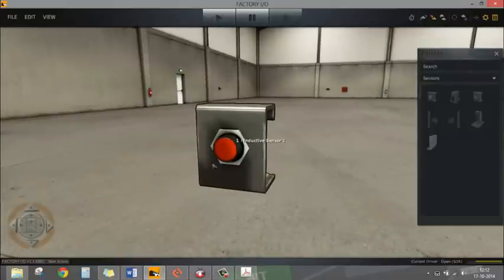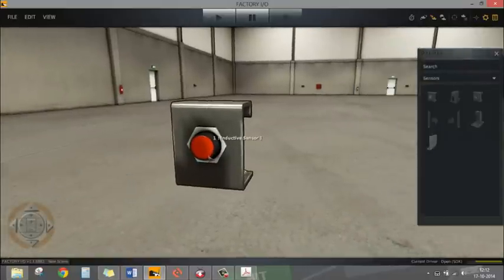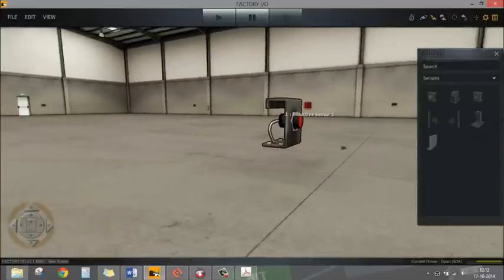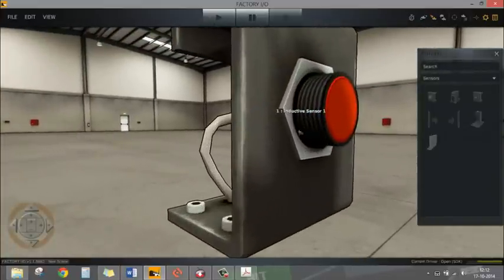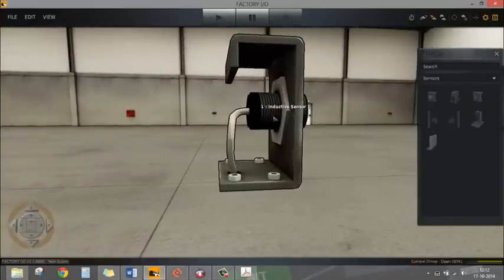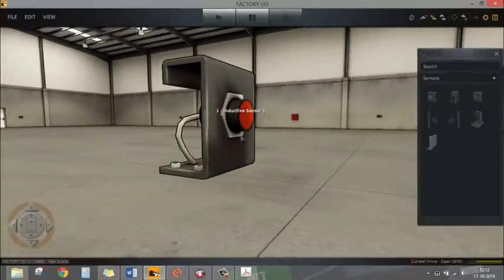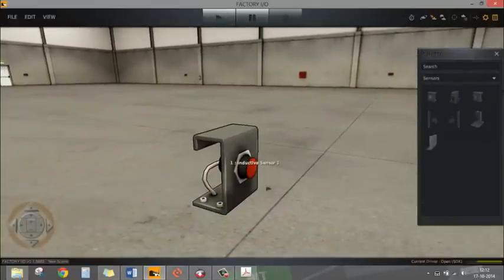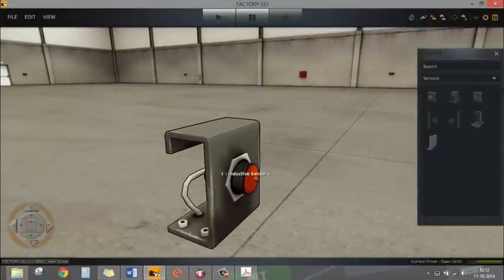If any conductive material passes across this field, eddy currents are produced in the material. That affects the EMF around the sensor. We have an operational amplifier inside it, with comparator signals which sense that there is an object because its field is disturbed. So it detects that there is a metallic object in front of it.